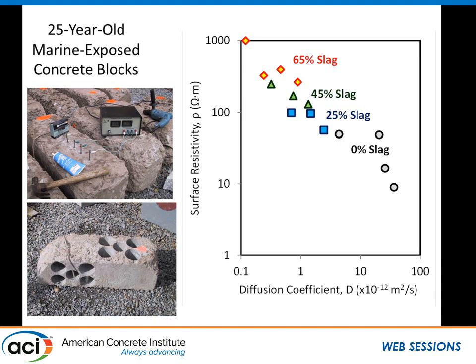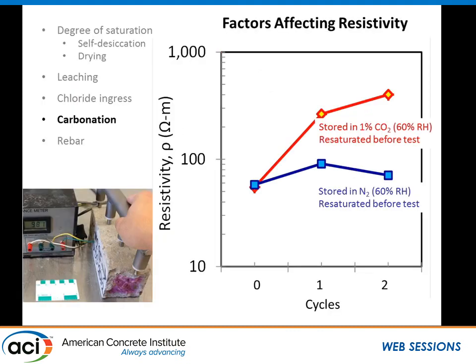Of course, a reasonably good correlation. You're crossing many orders of magnitude with both measurements, of course, and you can see the impact of having a supplementary cementing material in there. But I did also want to reflect on some of the things that start to skew this relationship between diffusion and electrical resistivity. One of them is carbonation.